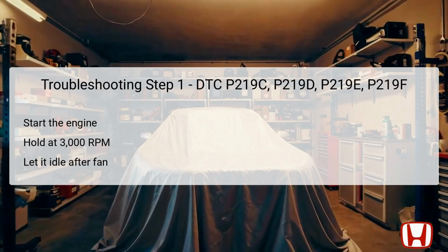After reaching 3,000 RPM, the engine should be allowed to idle until the radiator fan engages, which signals that the cooling system is operational and the engine management system is maintaining proper temperature. Observing these conditions is fundamental, as the engine's performance must be closely monitored during testing.